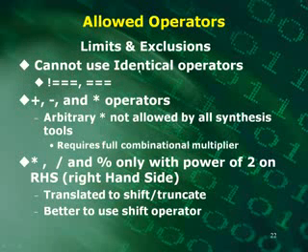You can't use the identical operators, if you remember those. Arbitrary multiplication is not allowed by all synthesis tools because it requires a full combinational multiplier. So you're going to have some limits if you're trying to do multiply and divide also.